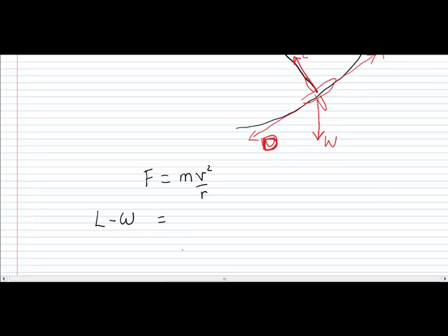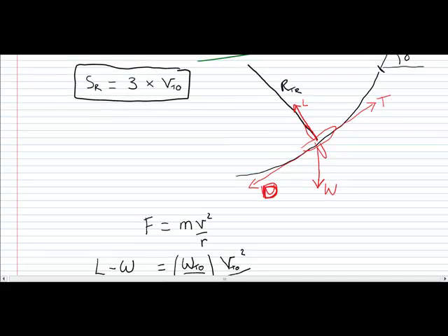The mass of the aircraft, obviously we are burning some fuel, but it's effectively still the takeoff weight. So that's our mass. We'll assume again that we're still travelling at the takeoff velocity through this period. Obviously this gets quite a bit more complex if we take into account that the aircraft is still accelerating through this phase, so we'll keep our life simple. And the radius is this R transition that I've defined up here.